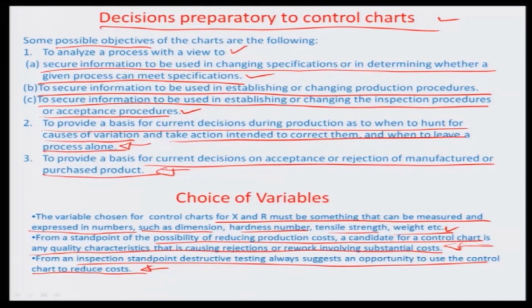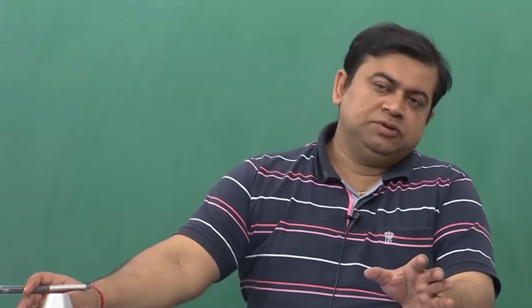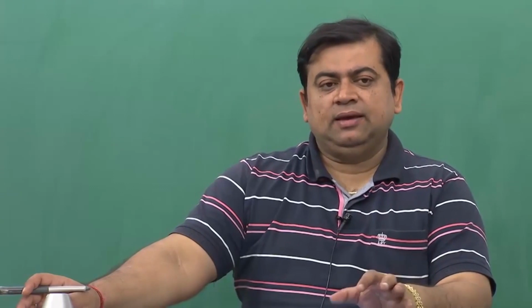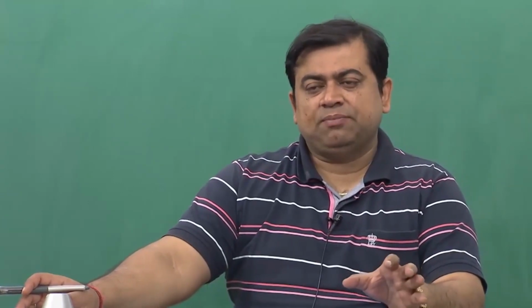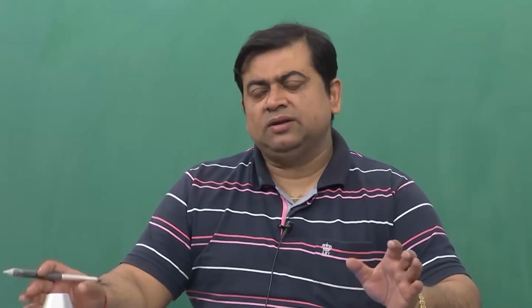So, in a production process, if all the samples are measured, you are not going to have anything at the end of the day. Therefore, on a subgroup basis or on a certain frequency basis, you could take a sample which could be 1% of the whole production lot, and if the subgrouping and the timing of the subgroup selection is done in an appropriate manner, this 1% should be able to give you a fair estimate of the whole population.